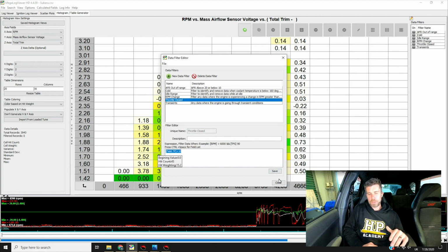Now this does get a little bit complex because you are going to need to go through and modify these based on what the parameter ID is actually called. So in that case, you can see the field is labeled TP. I think I'd actually done this for some ECU master tuning. In the Subaru ECU, we don't have that parameter TP, which is why that's not valid. We instead have throttle opening angle, I think from memory it's called.